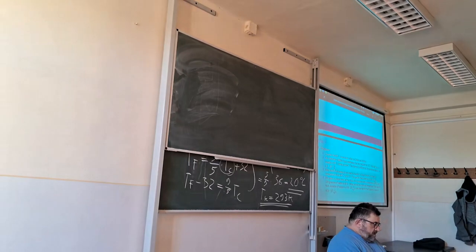Okay. Next, an aluminum 100 kilometer long transmission line was installed at 0 Celsius. What will be its length at 40 Celsius during summer? The thermal coefficient of the aluminum material is this. Usually these thermal coefficients are quite small. So this means from 1 meter, 0.1 millimeter.